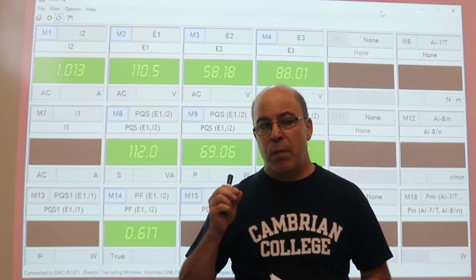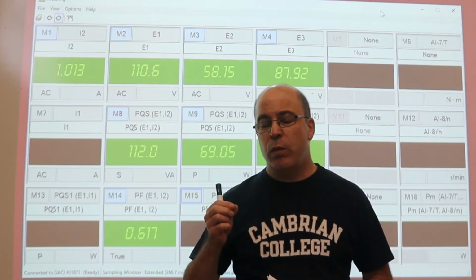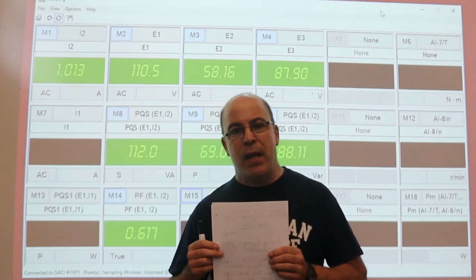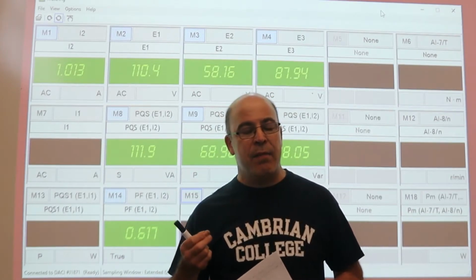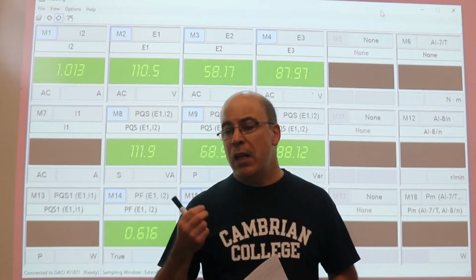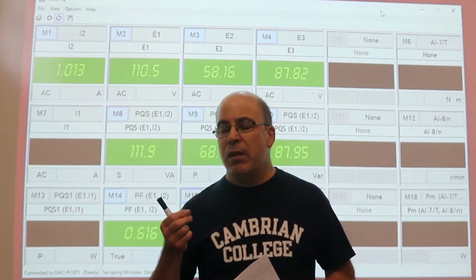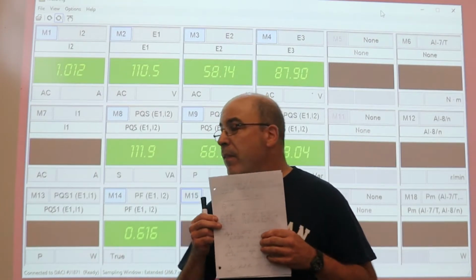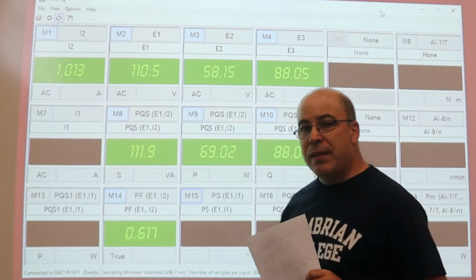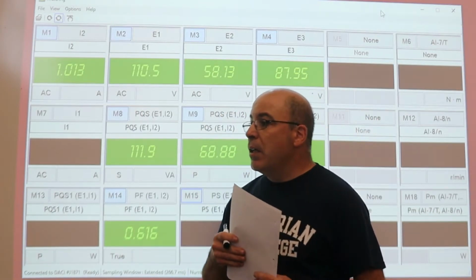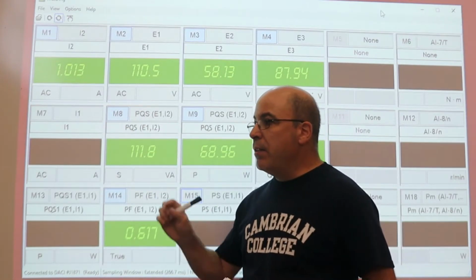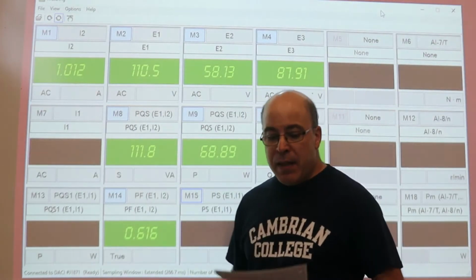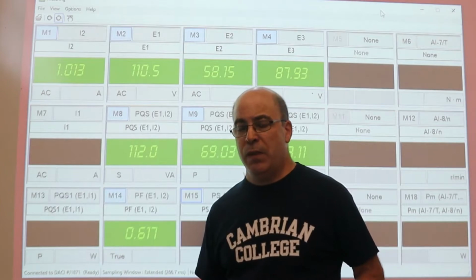I want people to remember that inductors that you work with in real life, as opposed to what's in calculations, are not perfect. Inductors inherently have a certain amount of resistance. They are coils of wire, and as a result there is no such thing as a perfect inductor. The calculations are pretty good, and you can see that there is a slight discrepancy. Again, I don't have the ability to fine-tune the value of resistance. I took a reading. It was not 57.1 ohms, it was 56 ohms.